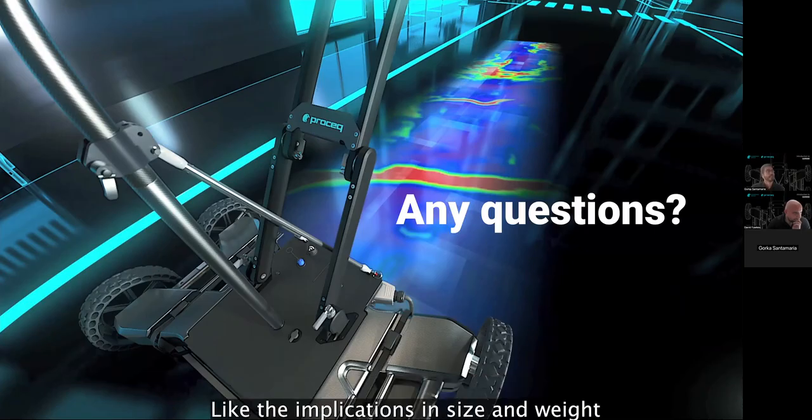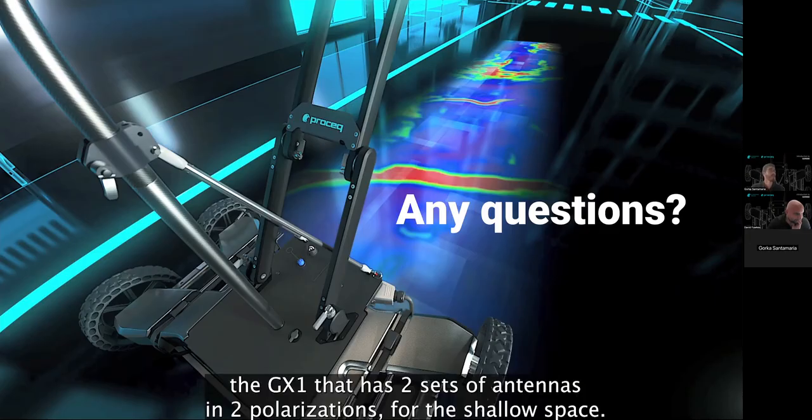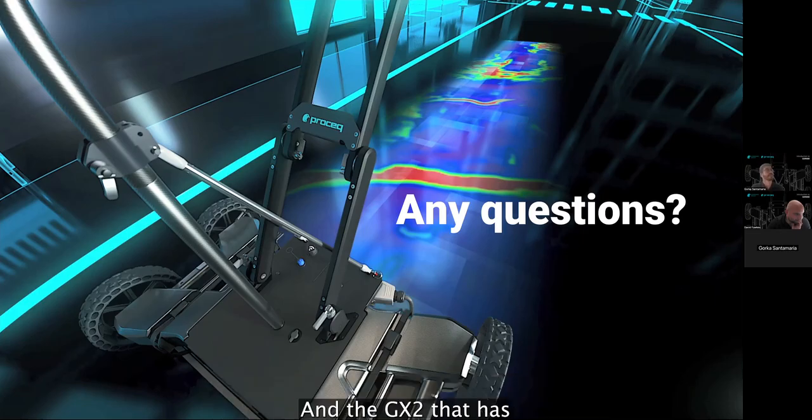The implications in size and weight do not get compensated by any tangible benefits in terms of detection or mapping. So that's the reason why we have two identical modules from the outside: the GX1 that has two sets of antennas in two polarizations for the shallow space, and a GX2 that has 11 antennas or 11 channels in one polarization for deeper objects. And that would be it.